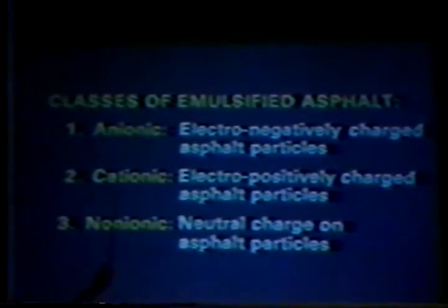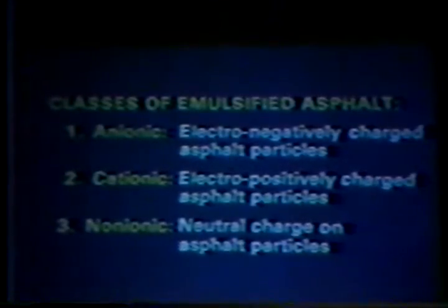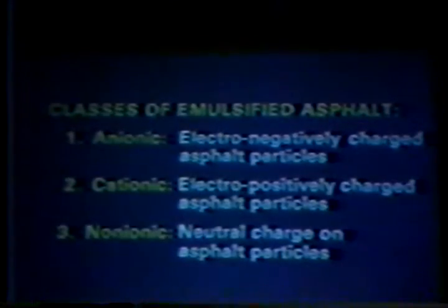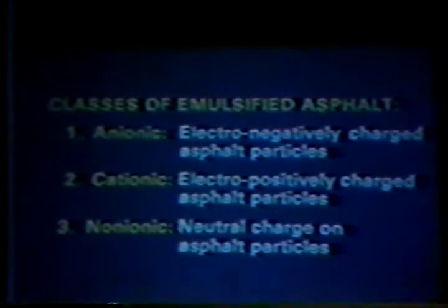One way to remember this: the cationic is positively charged, the T reminds me of the plus, and anionic is anti. It's important when you're making cold mixes to know whether or not the emulsion you are going to use is going to mix with the aggregate source you're using. And that's why it is important to identify the 2 different types.